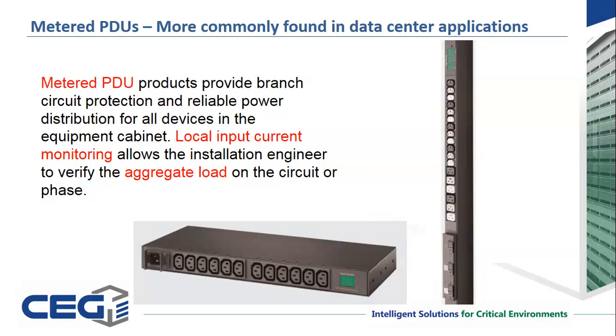A common problem is that people look at outlets that aren't used and figure that there's available power there. If there's an open outlet, I can plug something into it. Not necessarily the case, and unless you have a meter that's telling you that, you don't know. The last thing you want to happen is someone to trip a breaker upstream and take down an entire power strip or an entire cabinet because they thought there was power available in a receptacle and it was already maxed out from everything else that was plugged in.